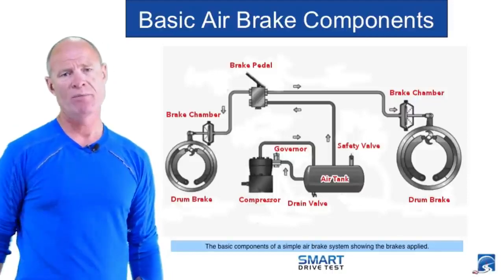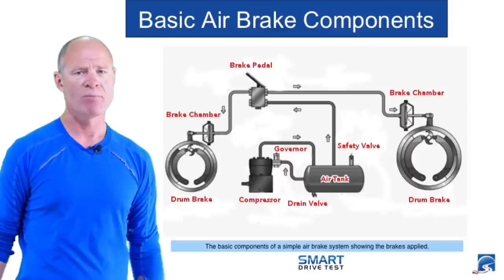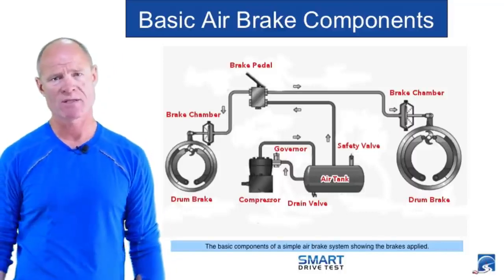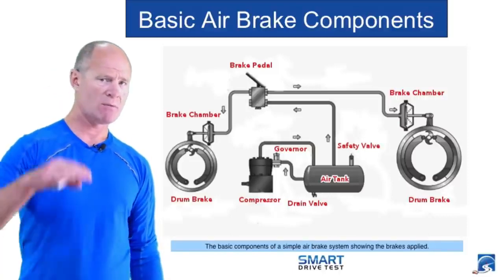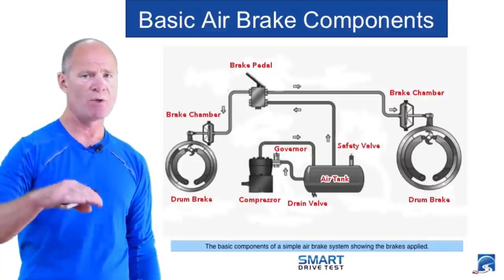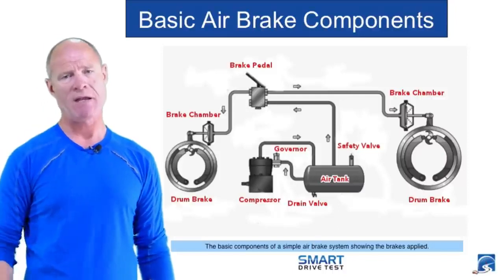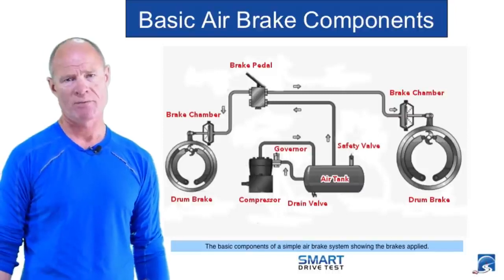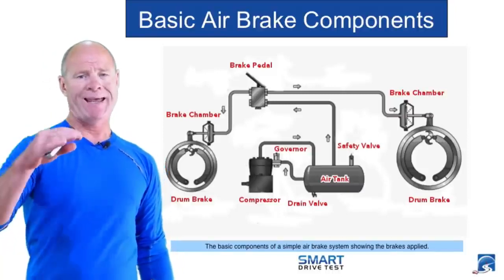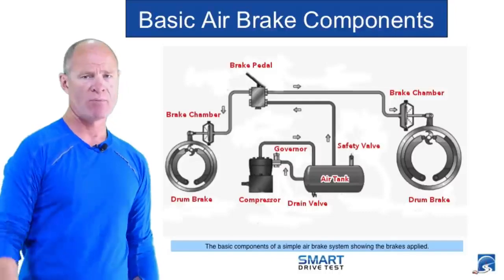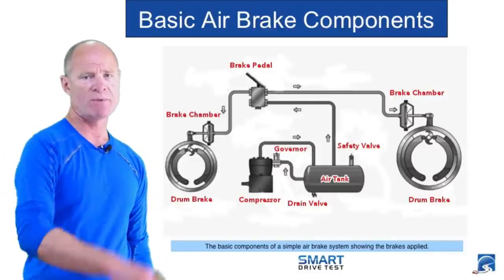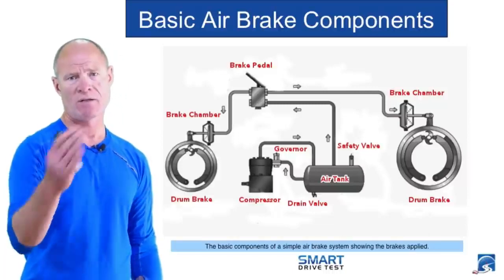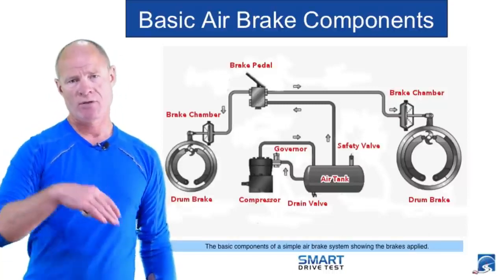The system goes down to a minimum air pressure. It puts the compressor back into the load phase and loads the system. In Ontario and some other places they call it the cut-in. System goes back up to maximum pressure. We know that it's at maximum pressure because the air gauge needles stop climbing, and the system is between 105 and 135 pounds per square inch. At maximum pressure, the air that the compressor is generating is simply pumped into the atmosphere. We either call it the cutout phase or the unload phase. So the governor controls the compressor.